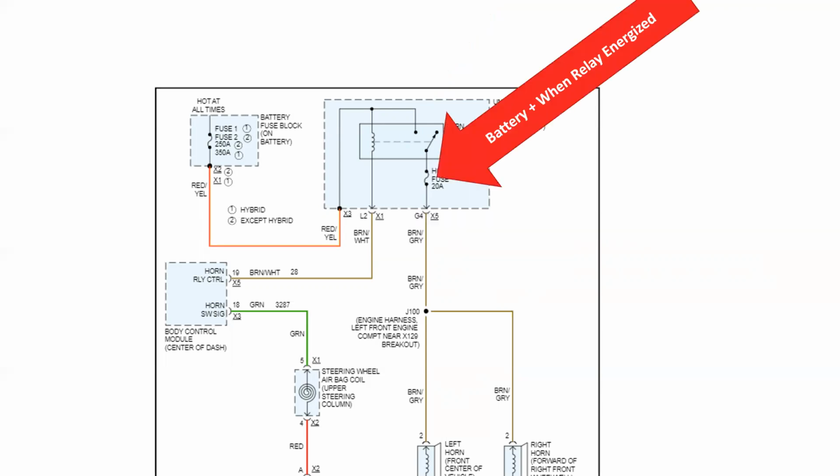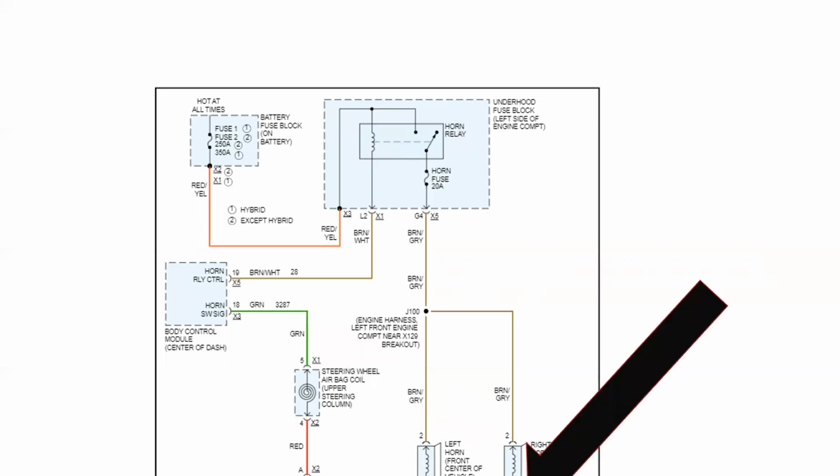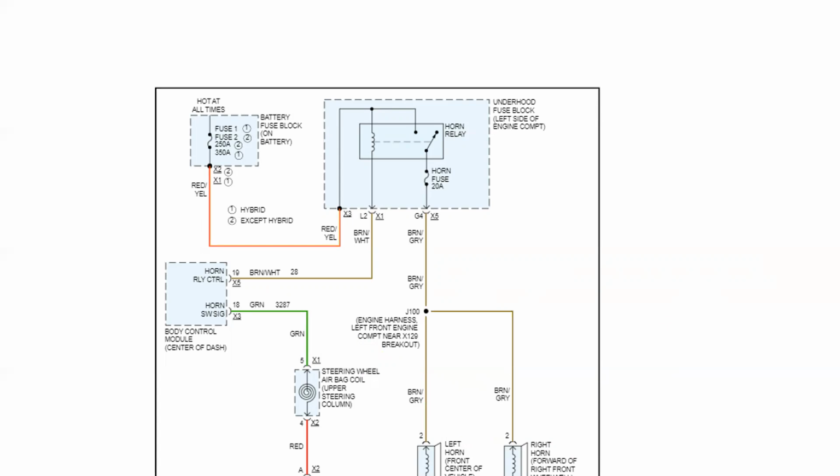On the other side of the circuit, I knew I had battery positive power coming from that same fusible link. But when I closed the switch, now I energized another fuse. And at that point, we ran battery positive power to the horns and from the horns to the ground. Nothing changed with anything that we discussed in relays. All we needed was a source, a load, and a complete path for current to flow, whether that was on either A, the control side of the circuit, which was a low current coil, or B, the higher current horn side.